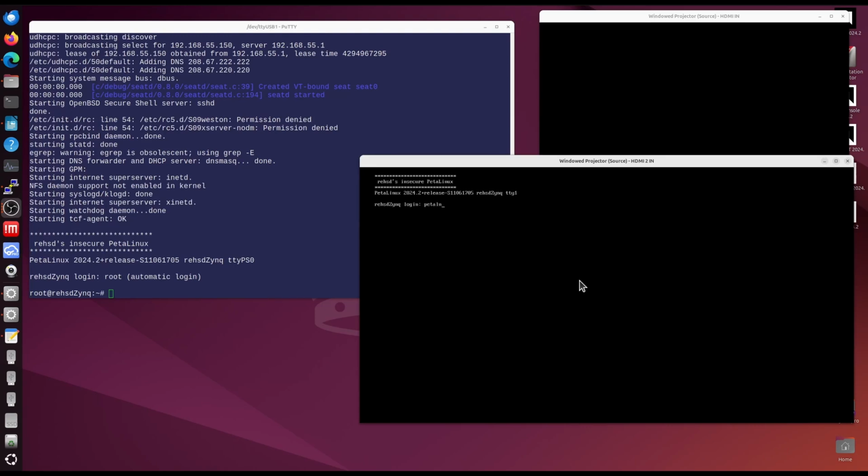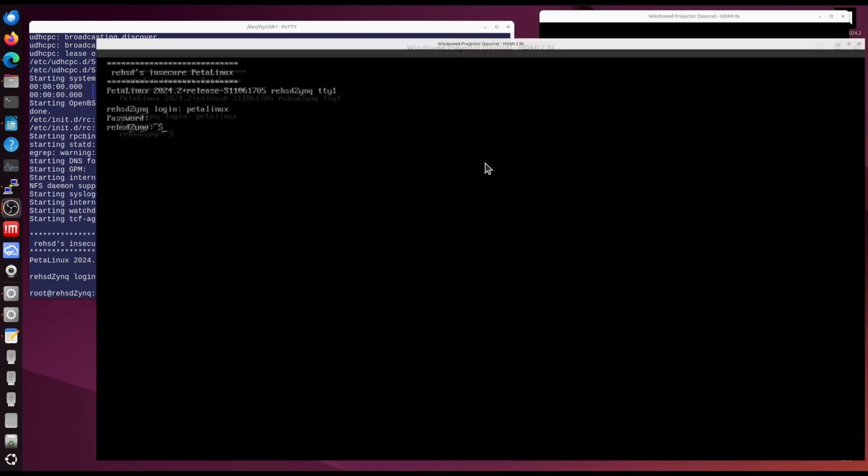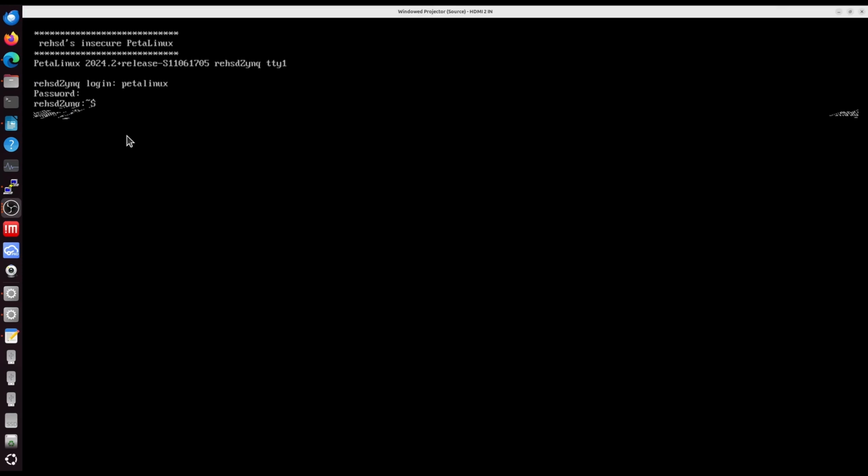But now I'm going to log in to PetaLinux, and now I can see that I've got some garbage showing up at a different point. I'll get garbage that shows up like at this point. I can see the timing, the buffering, something is way off. But that's different behavior than when I had loaded or tried to load the X server.